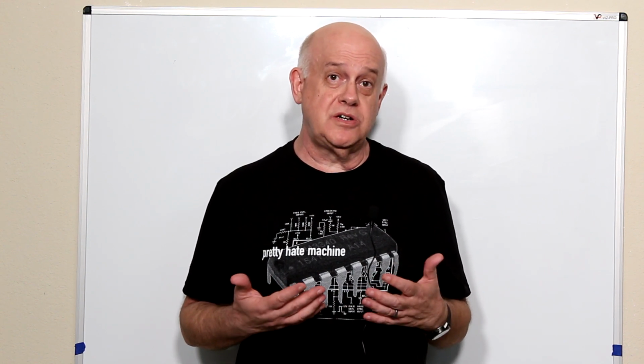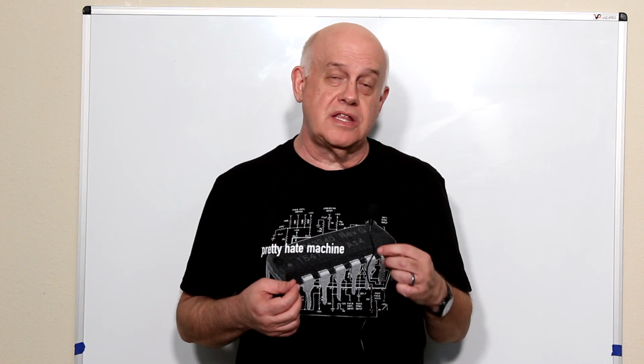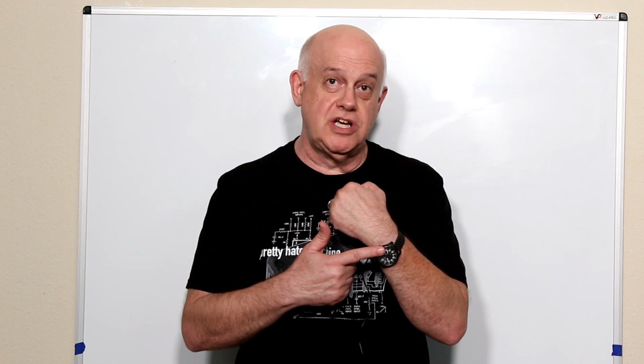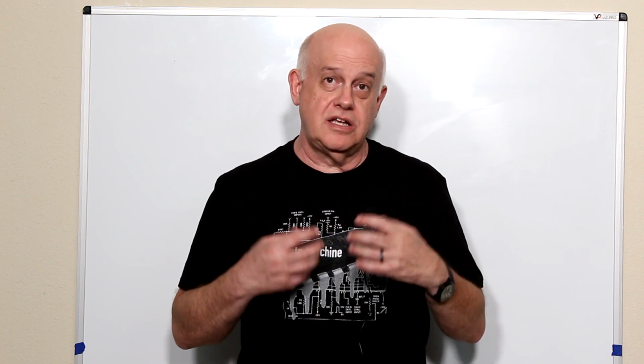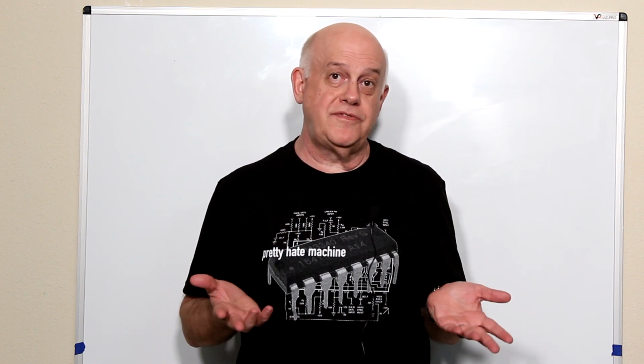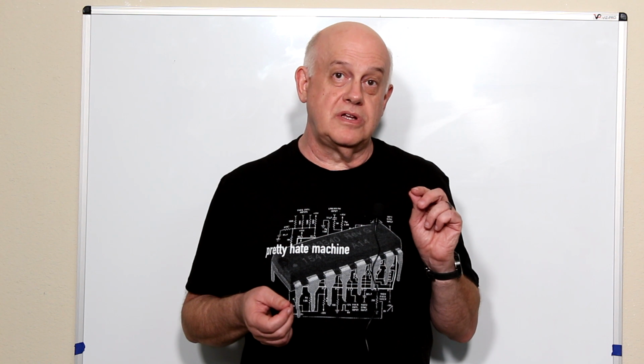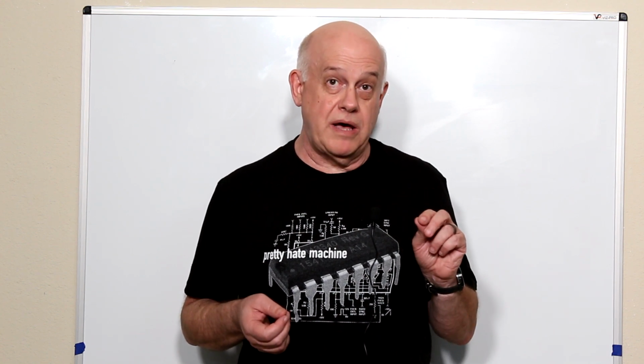Also, they have very low C sub L. The lower the C sub L, the less power they use. So if you're doing a watch, something battery powered, you want as long a battery life as you can, and one of the main ways to do that is to have a low power oscillator. So check out this app note that I wrote, and let's go to the web.